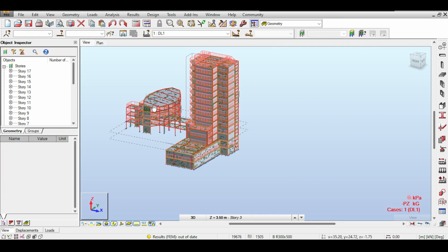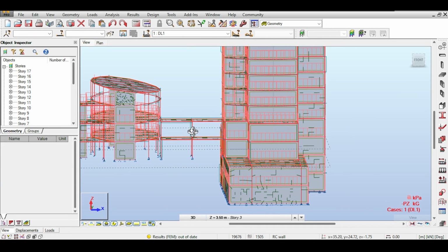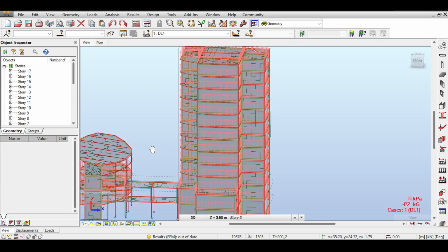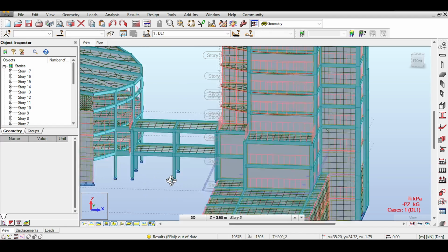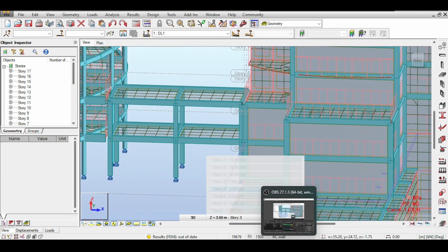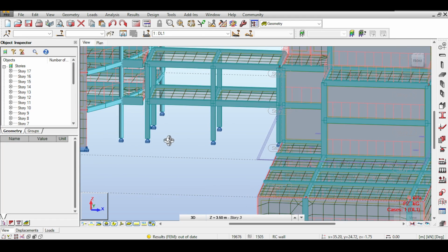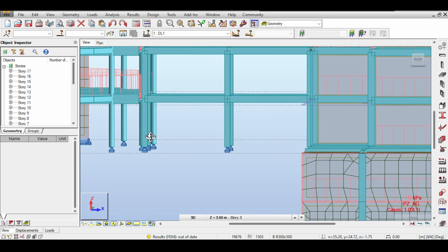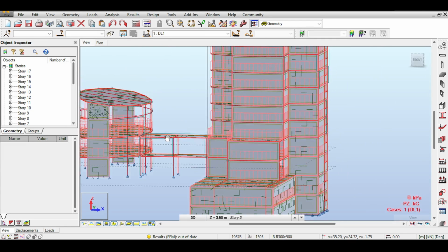What remains now is talking about the foundation and maybe give some slight advice about how to actually size your columns. Now, before I finish, I want to mention that we already have videos talking about the design of foundations, but those videos are basically one foundation at a time. This is a structure, so one interesting part of the structure is to notice that here you would have a foundation looking like an L shape, and you have to force the foundation to look like an L shape, and this is something I want to do next time.